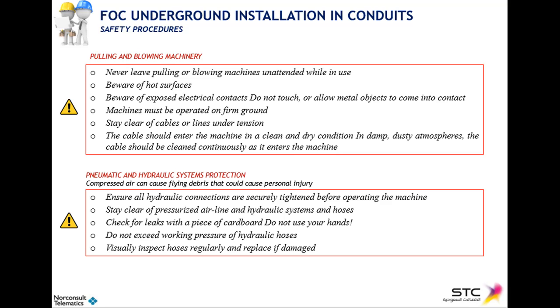Specifically on the pneumatic and hydraulic systems that are used for blowing, compressors and so on, they are carrying important pressure forces in the hoses and pipes. So pay attention to these points and make sure that the hoses are properly clamped and fixed onto their equipment.